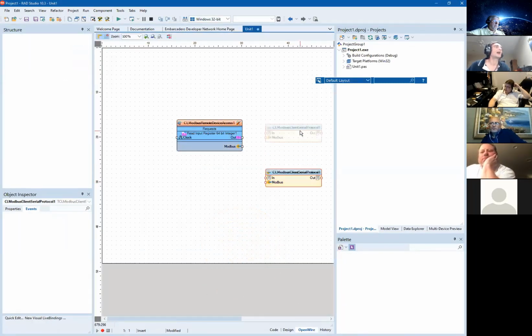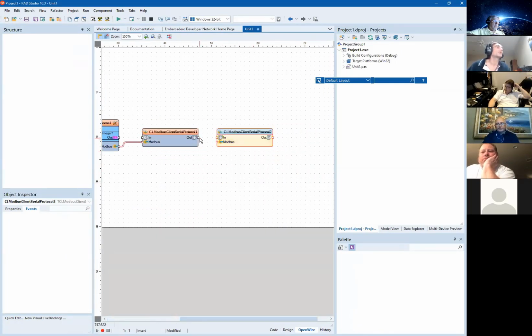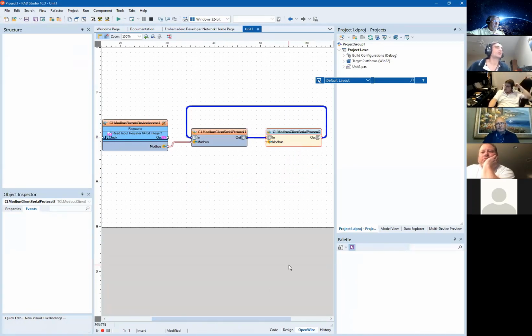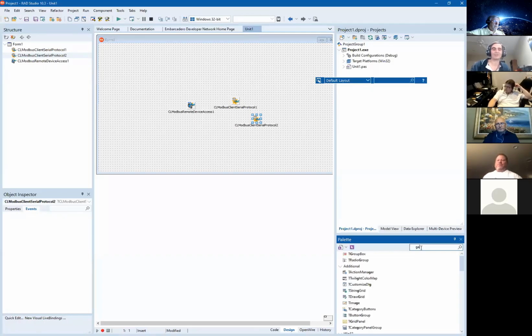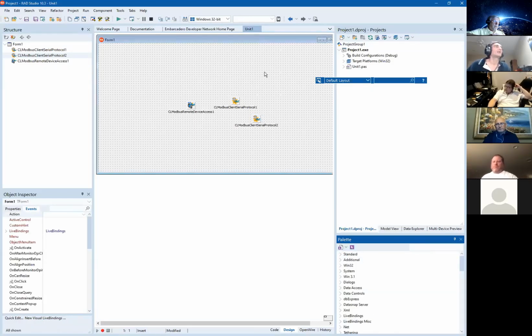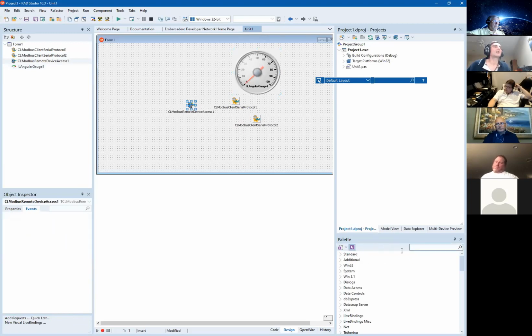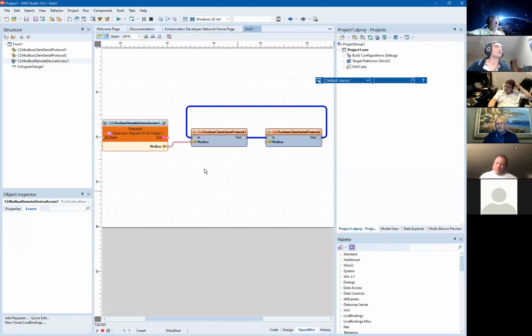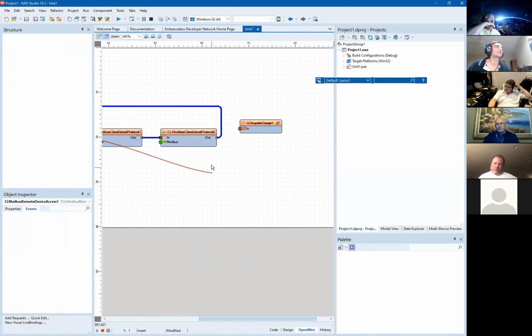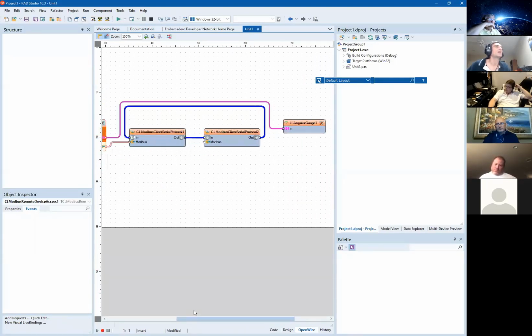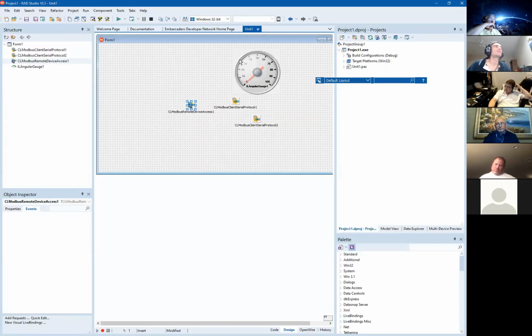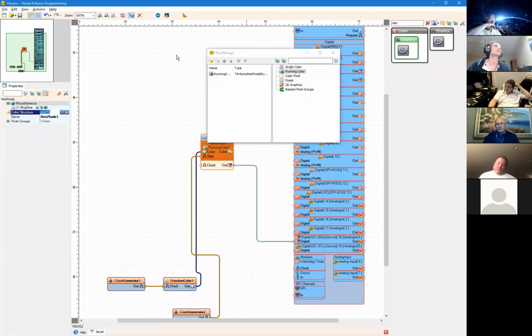And if we go here, what we can do is hook the inputs and outputs of our Modbus protocol to the serial, and add some gauge or something where we will display the data. Again, we can program this, but it gets a little bit out of scope and in the area of industrial environment. And now I can monitor either a PLC or an Arduino programmed with Visuino to become a PLC controller.